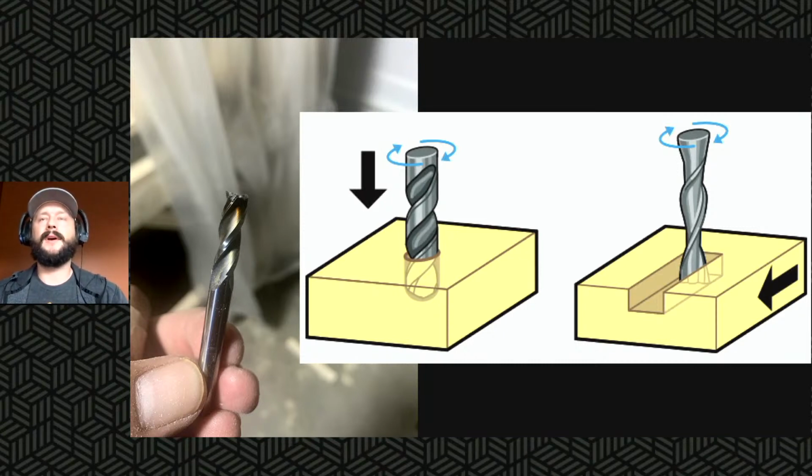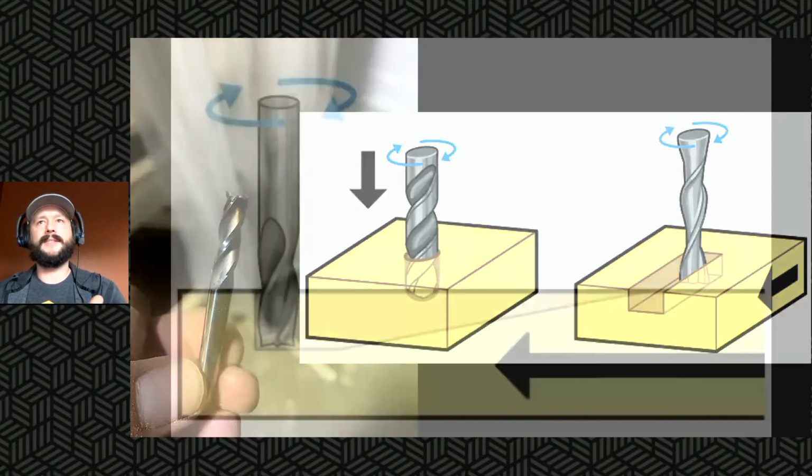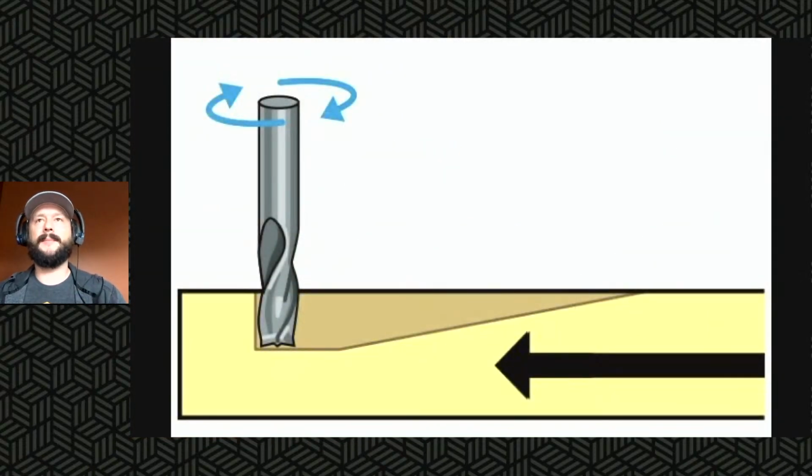Ramping requires a bit more of a change there, since you need to do either a zigzag motion, as you saw in the video from Brandon, or if you're doing a continuous closed shape cut, you can ramp in a continuous motion and then continue around in a circle, come back to the beginning, and then clear out the remaining parts of the ramp. So it required a fair bit of changes to how we've traditionally generated toolpaths in Easel to get to the point where we could actually implement ramping on all the various types of cuts we support.